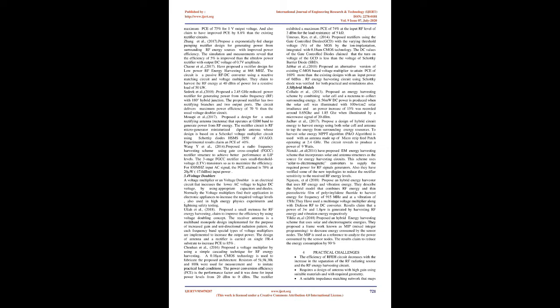Fellini et al., 2014, proposed an RF energy harvesting system with an improved dynamic impedance matching network, DYIMN. The DYIMN system was integrated on an FR4 substrate that uses discrete components and is capable of converting RF energy to regulated DC voltage that can power many wireless devices. The experimental results claim to achieve maximum impedance matching with an input RF power of up to +5 dBm. The circuit requires as low as -10 dBm of power to harvest energy from a source at a distance of 150 cm.